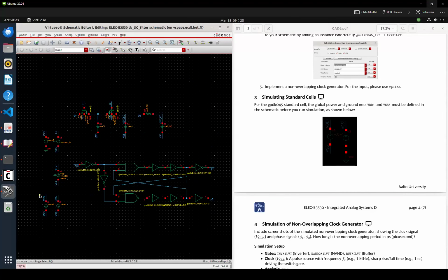If you simulate standard cells in a different process, for example, like GlobalFoundries 22 nanometer or TSMC 65 or 28, the procedure may be different. So it is not the golden standard for simulating standard cells. But for this PDK, we can simply build it this way.